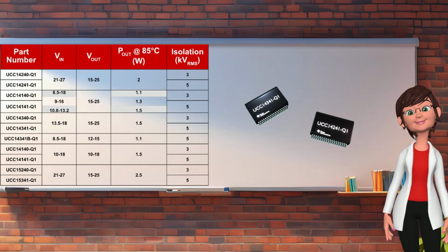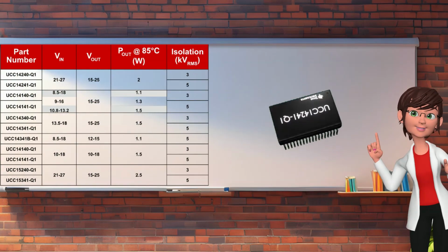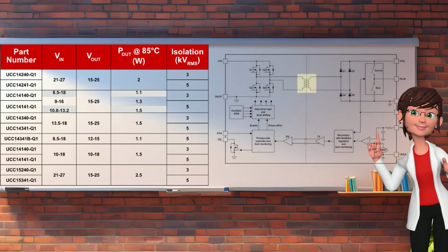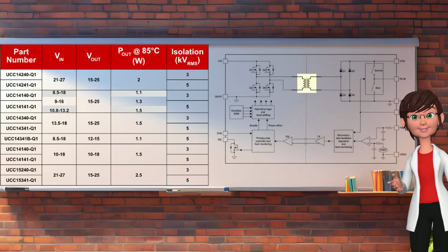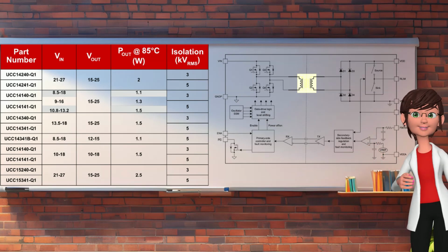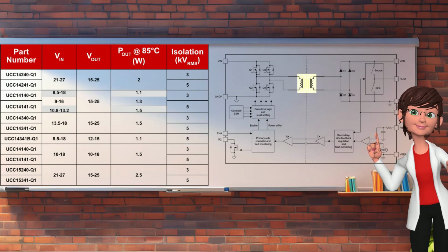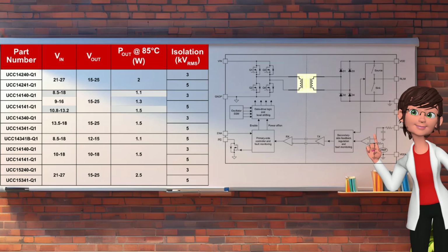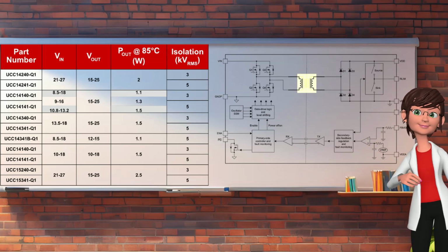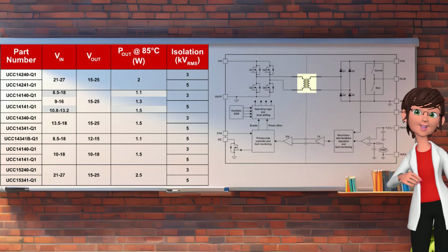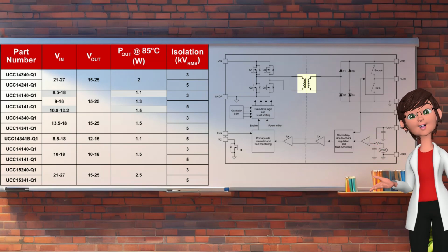One of the key culprits here is the integrated transformer. For the same input and output voltages, the distance between the transformer windings has to increase to support a higher isolation rating. The wider gap means the transformer has to be optimized to maximize efficiency, so for isolation alone, the transformer has to change to raise the isolation rating from 3 kV to 5 kV RMS.